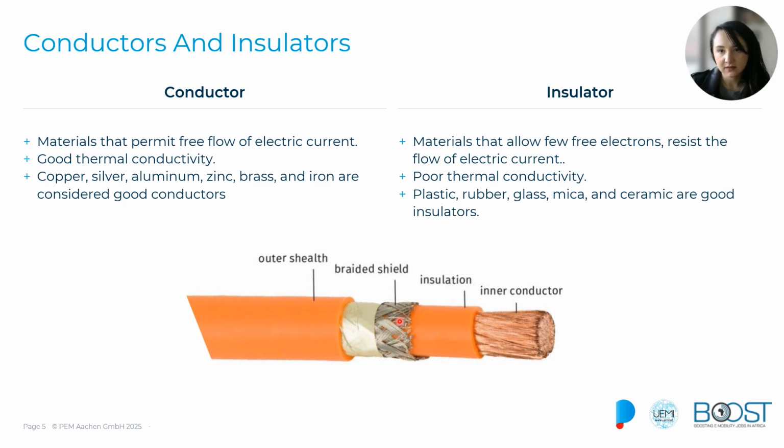Why is this needed? Since high voltage cables carry large currents, these large currents create strong electromagnetic fields. Those fields can interfere with any nearby electronic component, or also with the same components that we have in our vehicle, and that causes operational errors and failures that we want to avoid. So this shield helps us to avoid the electromagnetic interference in our systems. And at the end, we have an outer shield to cover our full cable.